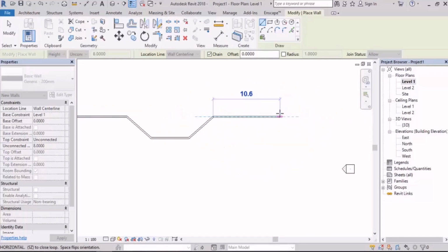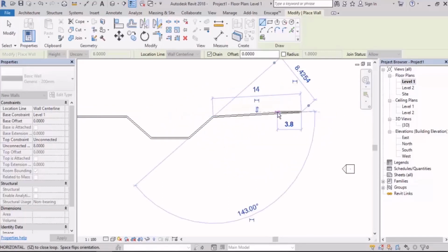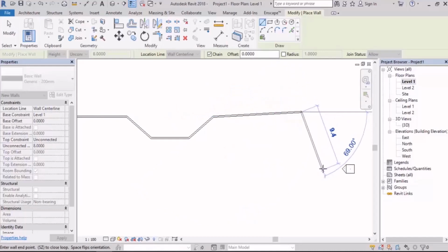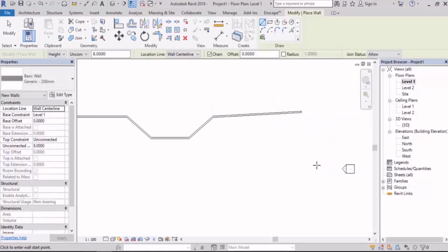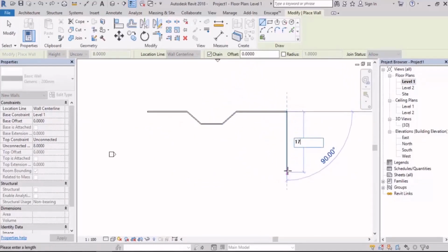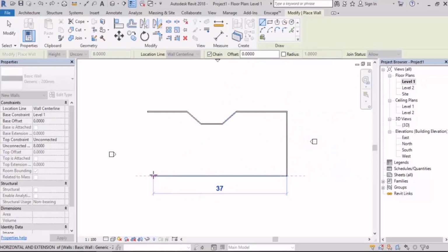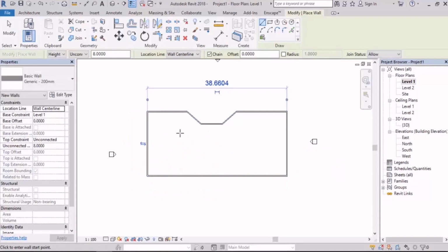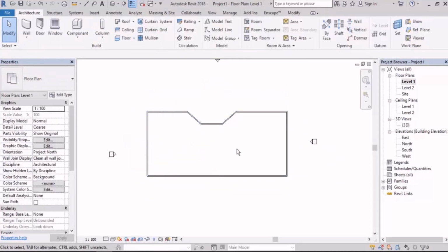Here again we put 14. You see it didn't get straight, and there's no U button for it like in AutoCAD when you undo. You have to click Ctrl Z and start all over. As you can see, I draw more walls. And that's it. Now, let's go and see other models of the wall and see how those work.